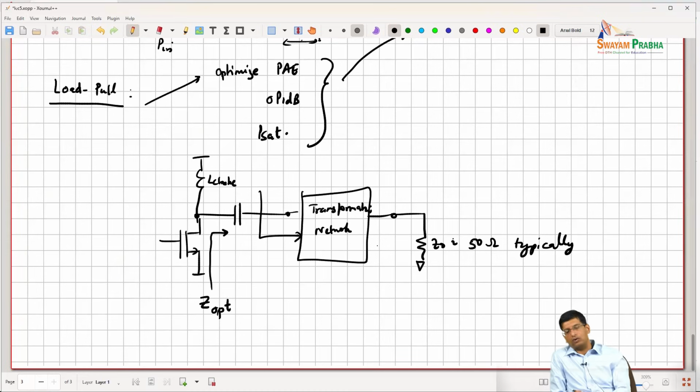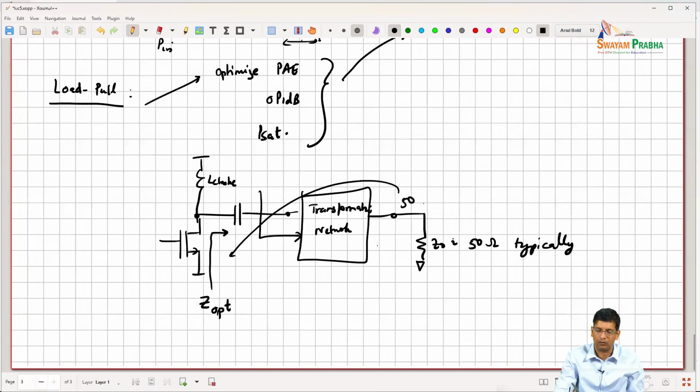So this kind of transformation network, we looked into wideband transformation networks. Quite often it is useful to have both wide bandwidth and impedance transformation, right? You might want to go from 50 ohms down to 25 ohms, for example, right? So we saw the design equations to do that both from a simple series stub matching and also from a higher order resonator approach, right?